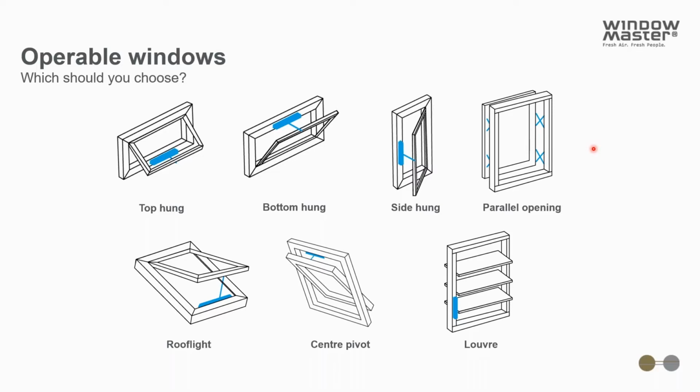The side-hung window is a good option for a single-sided ventilation solution as it presents a taller opening area. However, it can be more difficult to control the draft rate during colder conditions, and the side-hung window will also demand more space if it's inward opening. So if you have anything close by, it will, of course, need to be moved.